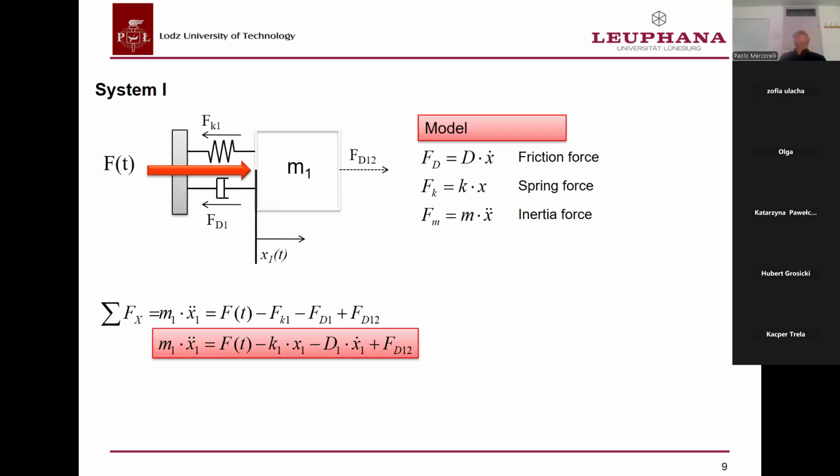because the friction force, in robotics and mechanisms, is a big chapter of modeling, also for the control. The reason is that what we see is really a simplification of the friction force. This model of the friction force is just a linear model, which, for instance, does not consider the static friction, but not only.